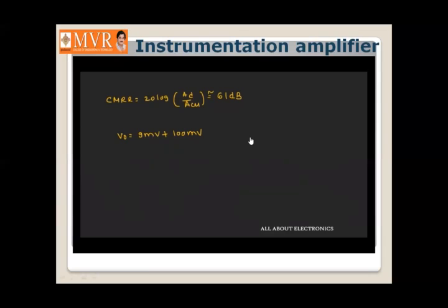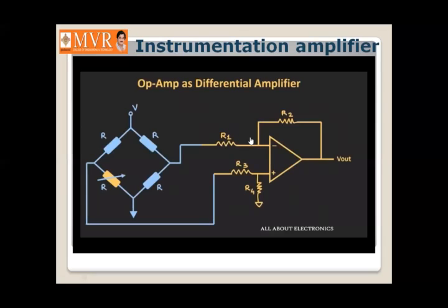So one way to solve this problem is to use monolithic ICs for this differential amplifier. One can use readily available differential amplifier ICs like AD629 and INA106. In these ICs, the resistors are fabricated in the IC itself, and the ratios of these resistors are matched quite accurately. So using these ICs, you can increase the common mode rejection ratio and minimize the error in the output voltage.